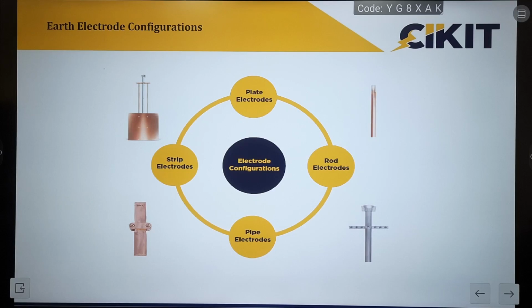It is commonly used for counterpoise earthing of transmission towers, and the second common application is type B earthing, that is ring earthing for lightning protection systems. In these two applications, we won't provide vertical earth electrodes. We simply connect the strips to the equipment and bury them at a depth of 500 mm.